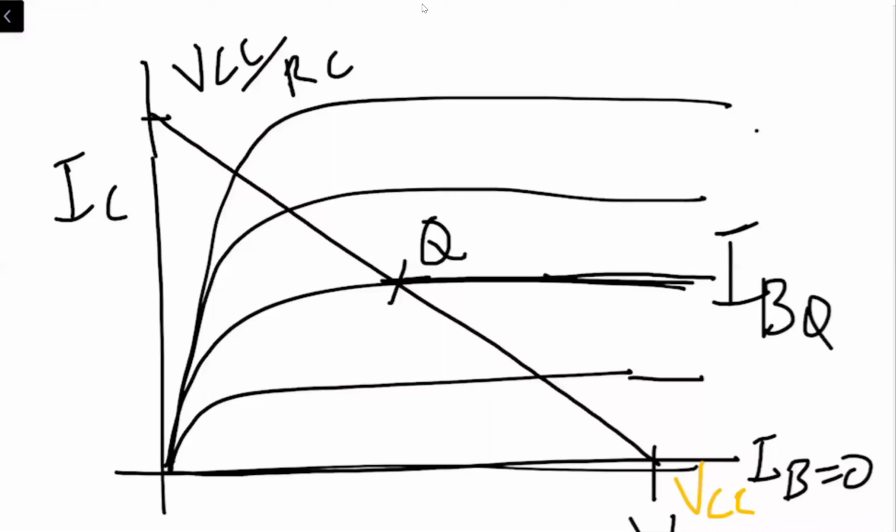So now the circuit is providing us the specific value of IC or specific value of IB. So depending upon that, we will be getting the point of intersection of the straight line with the characteristic curve. So whenever the characteristic curve is cut, we get the point of operation, which is the quiescent point or point of operation or Q point, right?